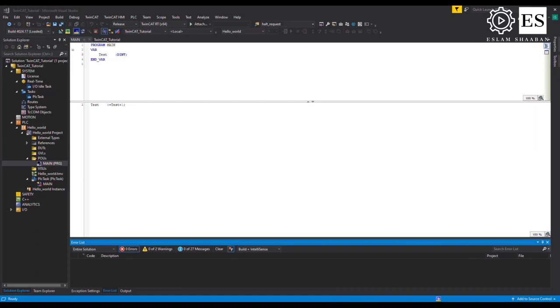Finally, some fun. The first step is to activate the configuration by clicking on Activate Configuration. In this step, TwinCAT compiles your code and sends the source file to the target system. In our case now, the target system is my local PC. Hit OK. TwinCAT asks if you want to start the system in run mode. Hit OK. Notice the taskbar shows the current status. Then log in to the PLC.